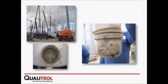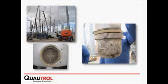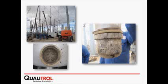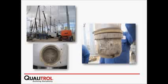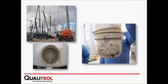So this is an independent pole 500 kV breaker, and whenever you have a PD, you're going to cause erosion of that contact. Before, it used to be a silver contact with copper in the back, and now you can see that it looks really bad. So the contact resistance would increase, and you can capture that with partial discharge monitoring. When you detect that, you only need to replace this part on the interrupter, and then put your system back in service. So the damage and the cost will be a lot less.